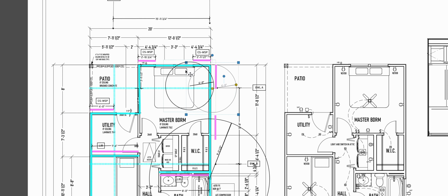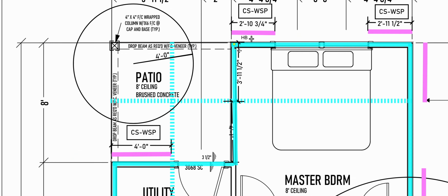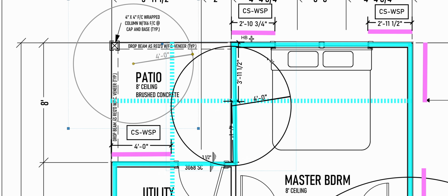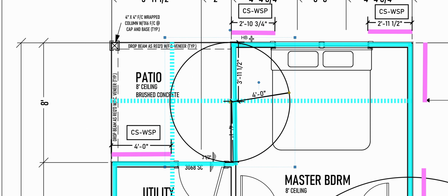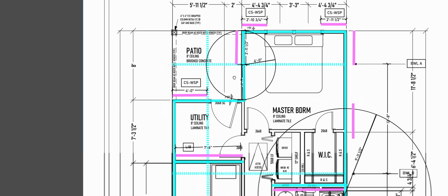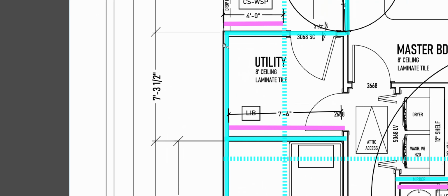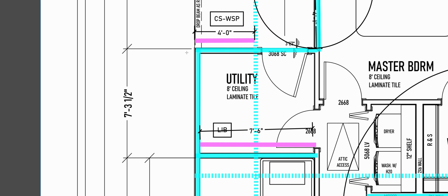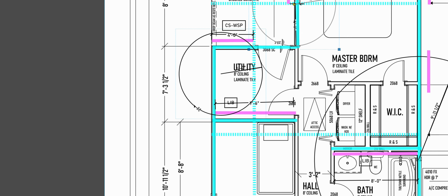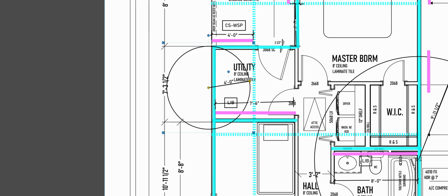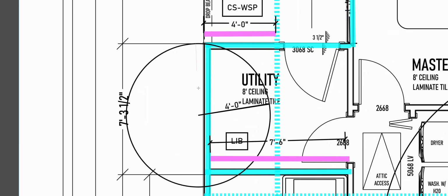Okay, let's check this side. Now, technically, the beginning of this brace wall line is not this corner, because my line's starting here. So I'm going to move this to about there. Do my first panel. And then I can go 20 feet down this imaginary line, but I have a corner here, so I'm just going to put a full sheet in this corner. And it's going to look like this.